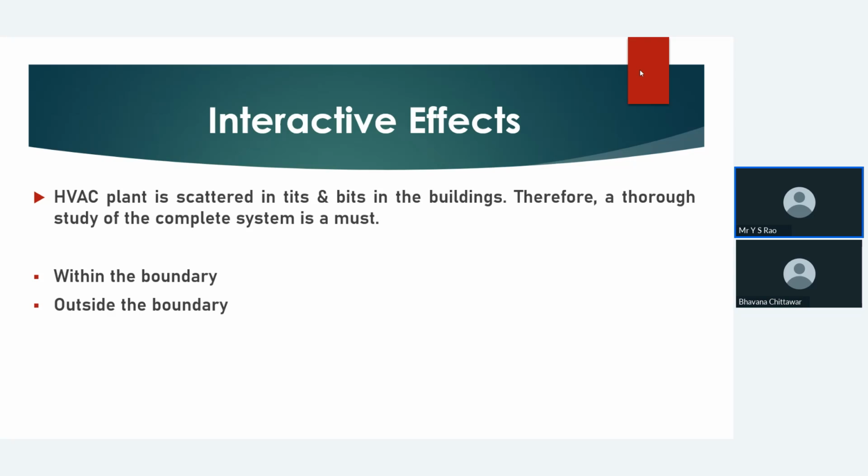And due to the interactive effects, mostly HVAC systems give troubles with the implementation of new ECMs. That's the reason why it's recommended that an energy auditor must verify the as-built drawing before producing the report, and study the system within the boundary and out of the boundary.